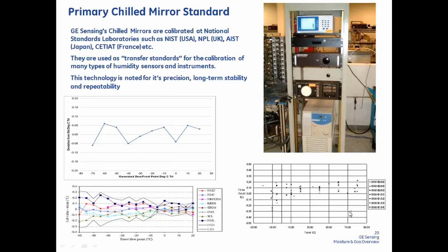The chilled mirrors at our facility are calibrated using an automated process. We essentially use LabVIEW and a generator to generate known values of dew point, and then those are intercompared against the standard. So the calibration system offers us a high repeatability and consistency in the products that are manufactured. We're also an NVLAP accredited facility, ISO 17025, and our scope of accreditation is online.